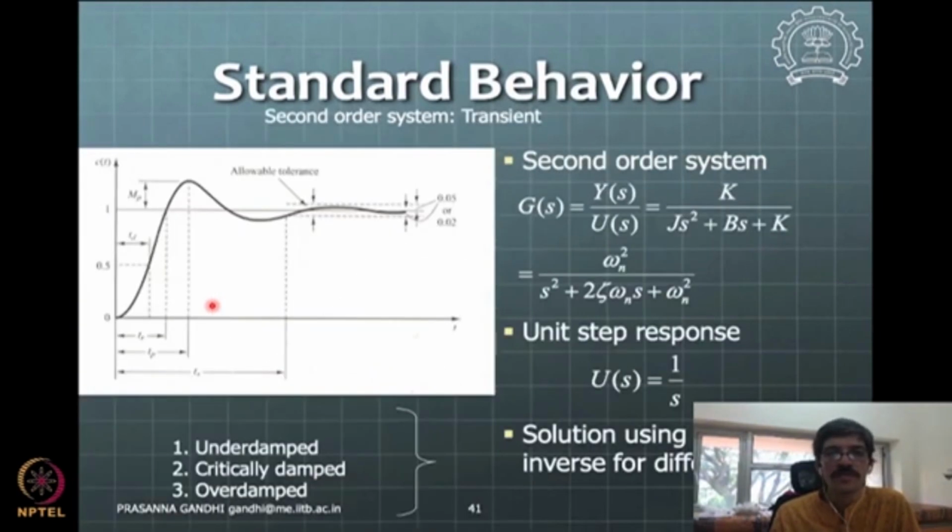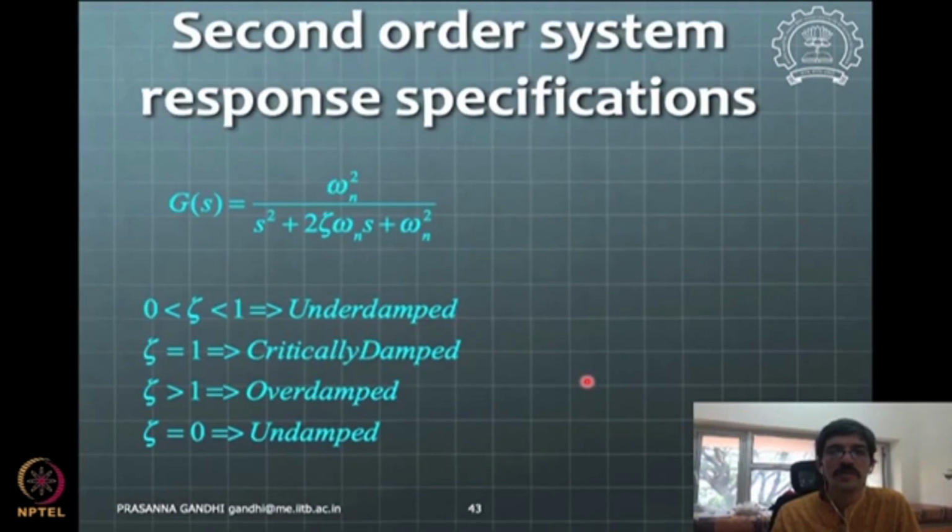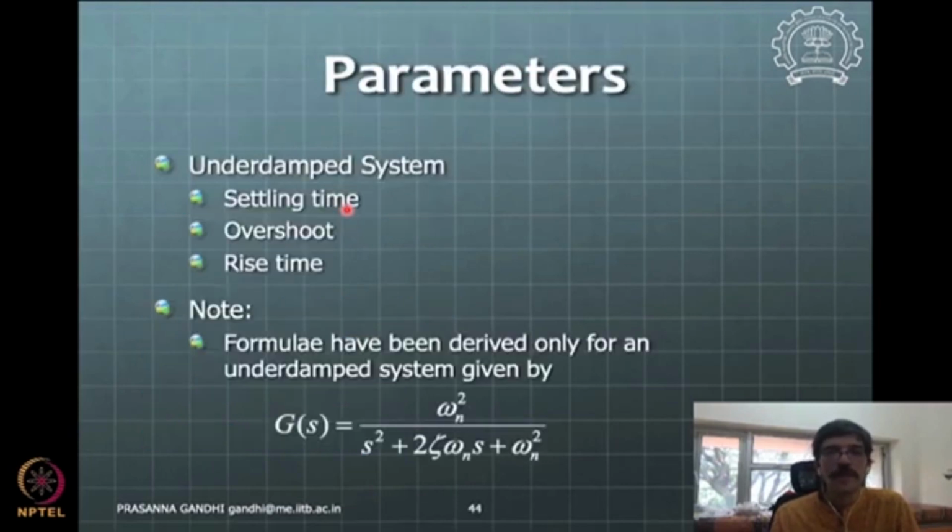And then we have the formulae for the second order system behavior, for maximum overshoot and settling time. This should also be handy to you. As we saw in the pendulum problem, for example, we can use them to set omega n and zeta to a desired value, or when you do the pole placement problem, the two dominant poles which you are placing close to the imaginary axis can have values taken from this.